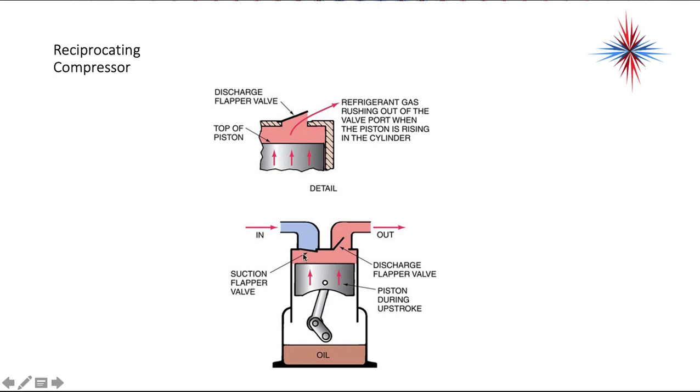However, this space between the top of the piston and the top of the cylinder, because that piston's not allowed to go up and hit the top of the cylinder, that is called my dead space. That is the reason why reciprocating compressors will never be 100% efficient. It's because of that clearance volume. It's why scroll compressors are considered much more efficient than the reciprocating.